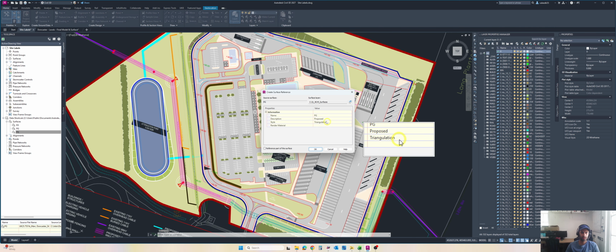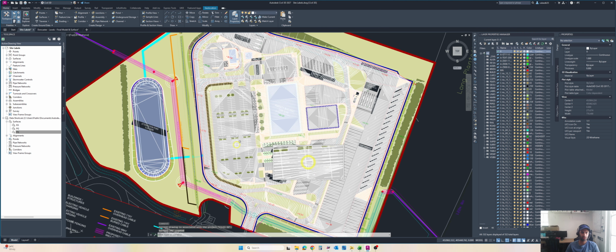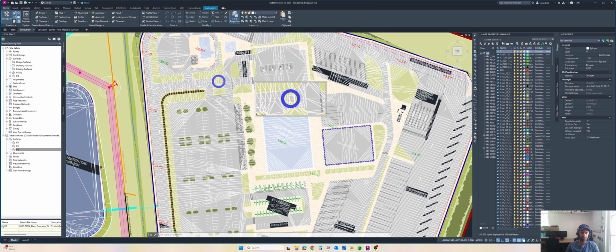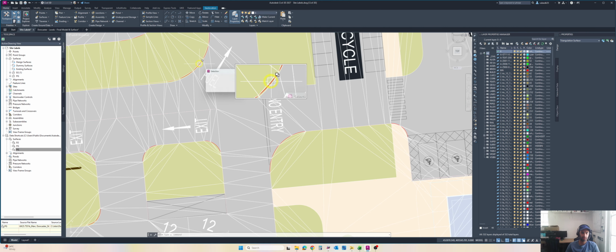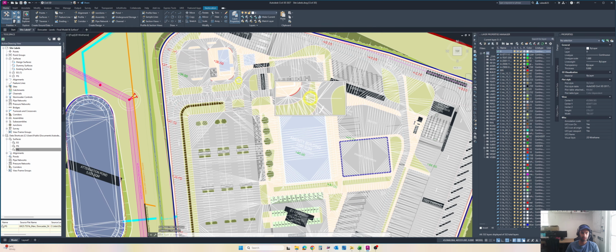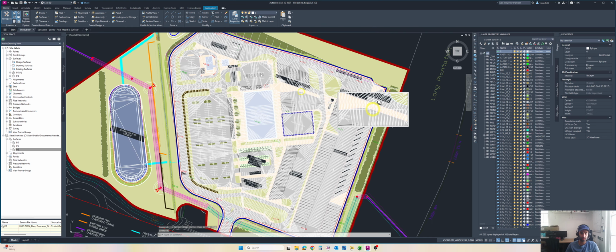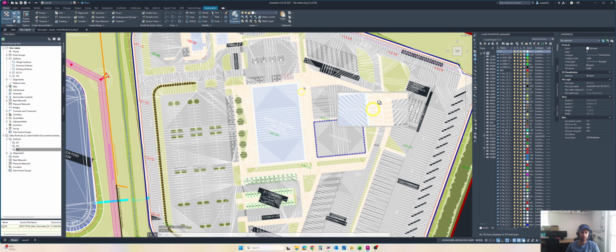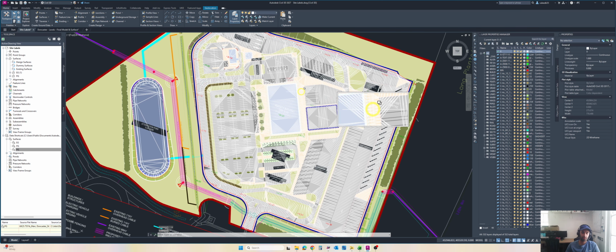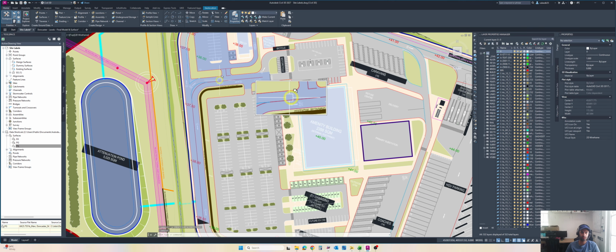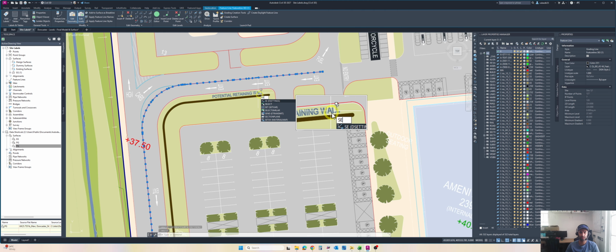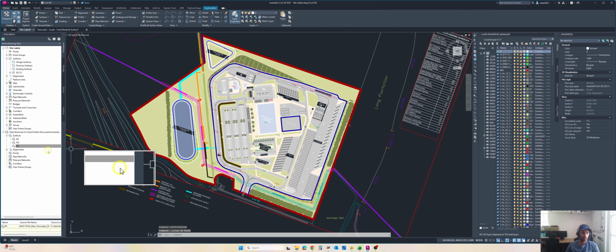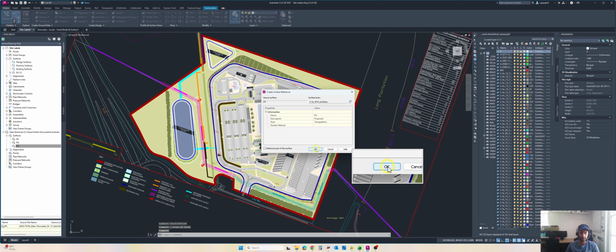This is the shortcut we have created, and I can go and say promote, and it will propose triangulation. Now you can see this has created the surface, and this surface didn't bring any of the feature lines. These feature lines, I think, are from the previous surface. We only deleted the surface, so I will select similar and delete all of my feature lines. Let's now do it again.